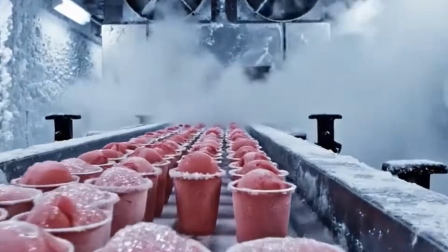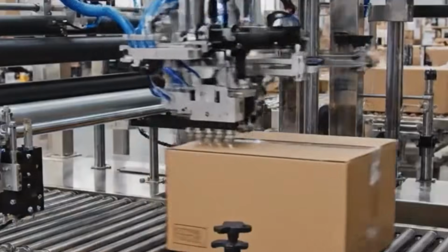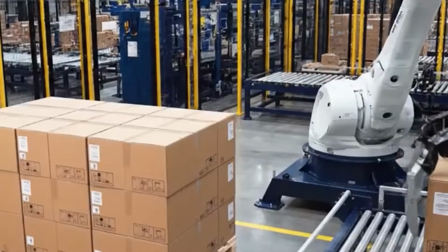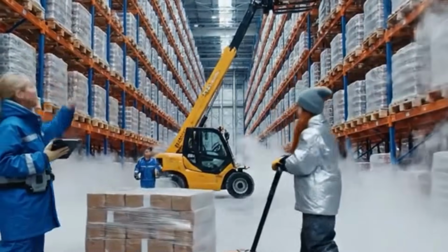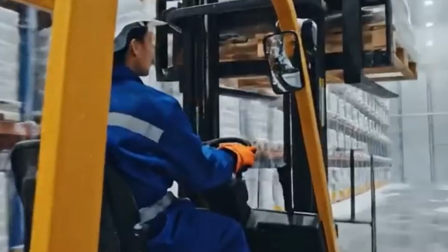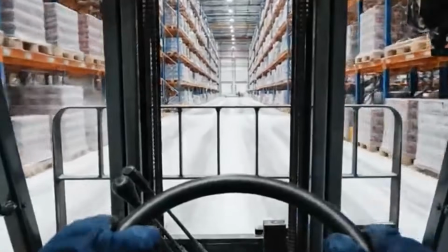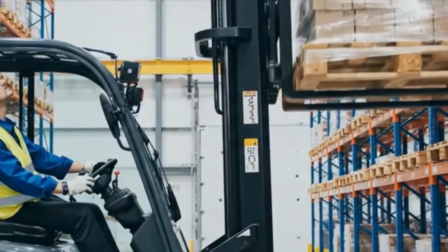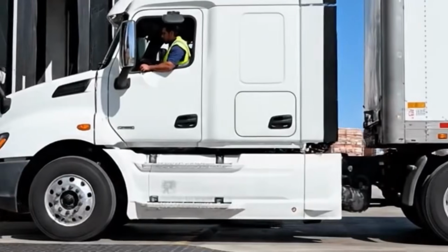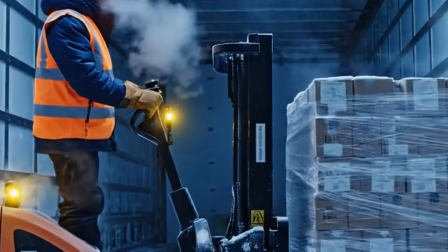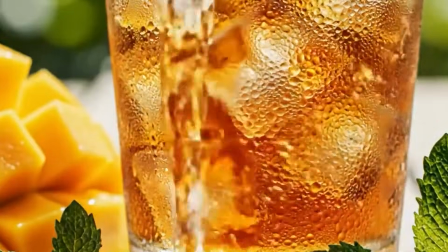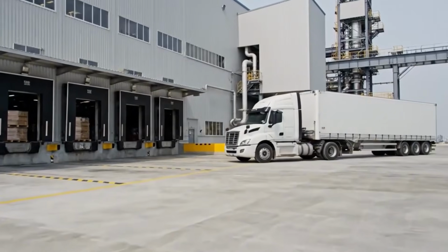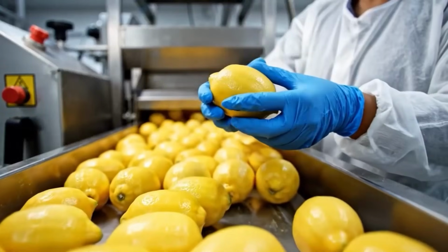The main batch tank is a large stainless steel jacketed vessel fitted with dual mode agitation, one high shear impeller and one slow speed anchor scraper to manage the simultaneous dispersion of powders and gentle circulation of the mix. The process begins by pumping deionized water into the tank. This water is processed through reverse osmosis filters to reduce mineral content and stabilize the flavor profile. Temperature of incoming water is held at 60 to 70 degrees Celsius to accelerate sugar dissolution and aid in the hydration of stabilizers later in the cycle.